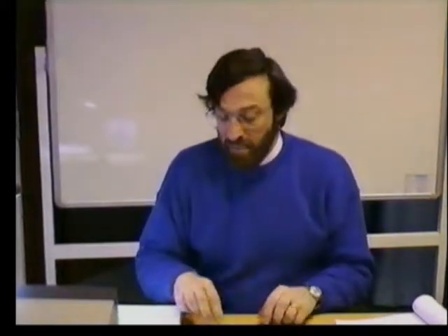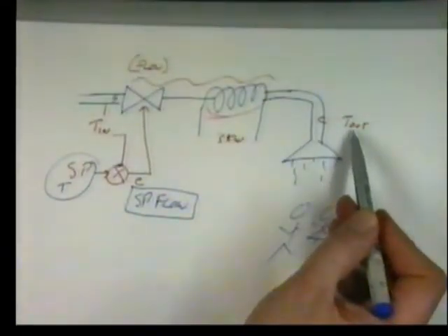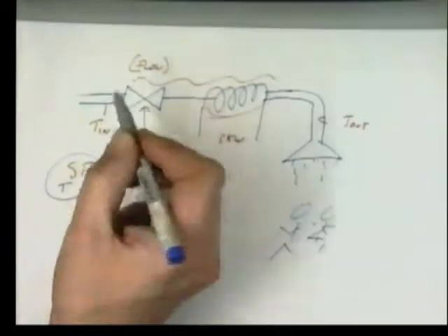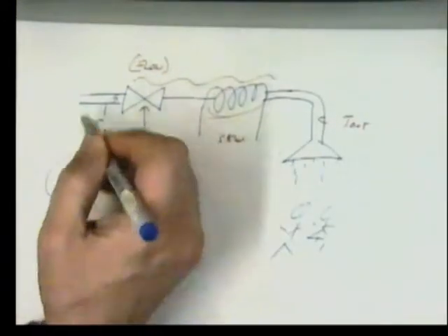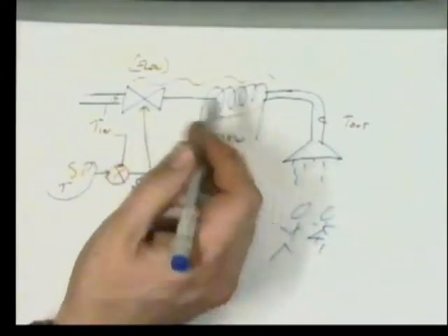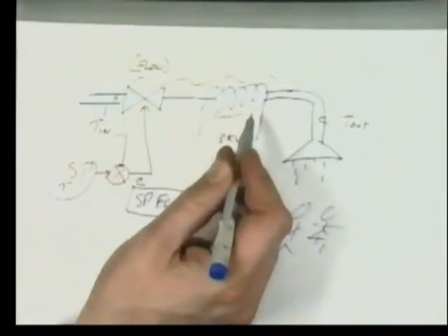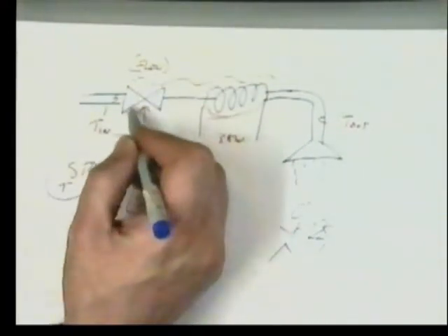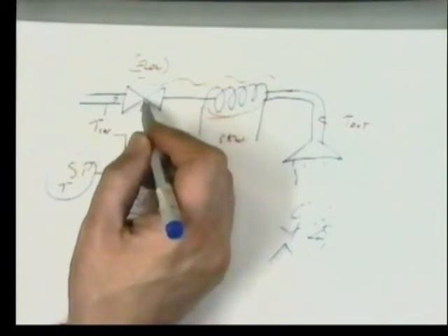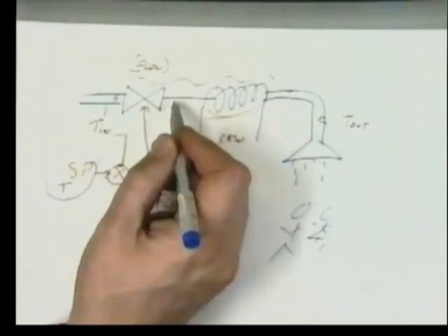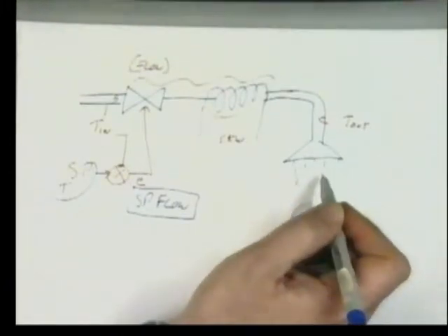We're trying to predict what happens, and this is called feed-forward control because it's predictive. It's in advance of the system. The feedback system looked at the output and fed that back. Feed forward looks at the inputs. It feeds into this algorithm everything we know about the system now, and we use that to predict how it will respond, and then we take decisions on the valve as to what position it should be in before this water has hit it, and then we get a much smoother control.